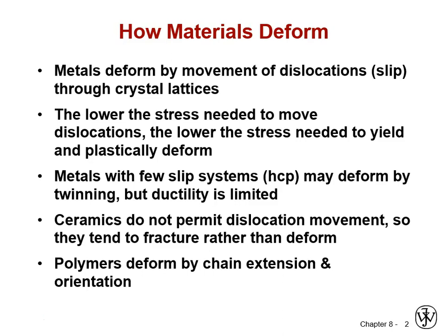Dislocations pile up and interact and don't want to use that slip system anymore, and then there isn't anything else to go to for that crystal system. So you will see twinning in systems with limited capability to support dislocation movement. If we look at ceramics, although they are crystalline materials and they do indeed have dislocations, it is very, very difficult to move them because the covalent bonding angles don't want to accommodate dislocation movement in the case of covalent crystals like metal oxides.